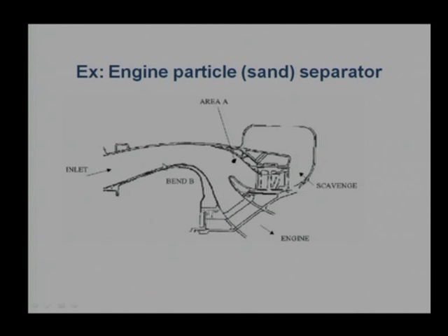That means air is sucked and supplied to the engine, but we know very well whenever the air is sucked, sand particles also come along with it. So, we require one effective filter, but we know very well if you use a filter over here, it will reduce the pressure. That means we have to boost the pressure, we have to compress the gas, and we need an extra system for that purpose.